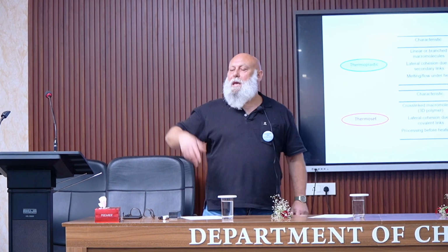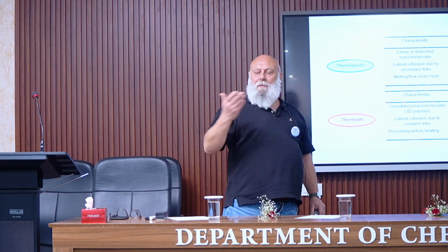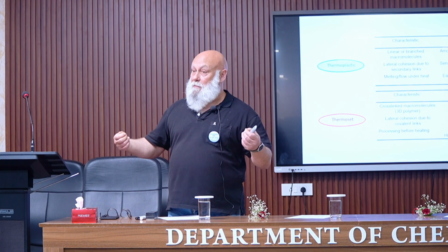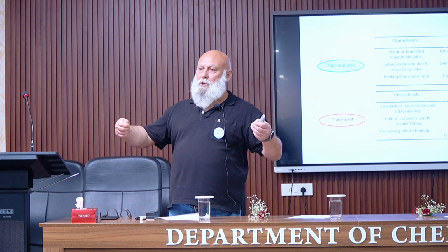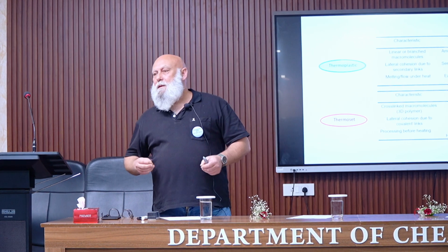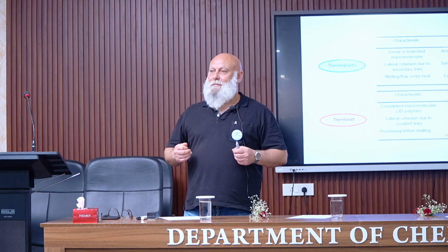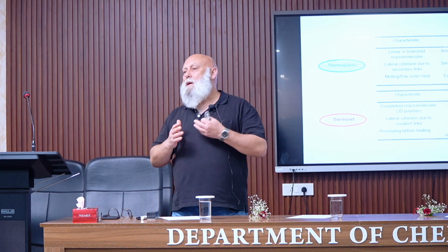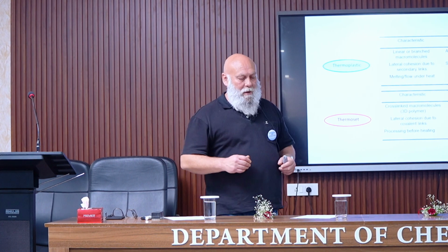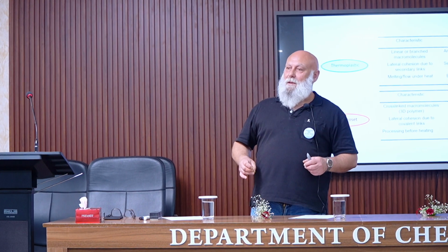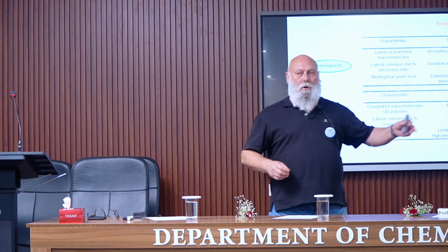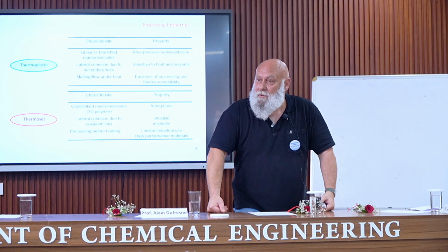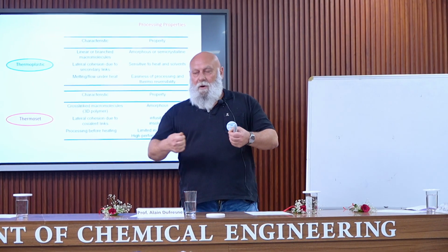The characteristic of an elastomer is that it is easy to deform, okay? And the deformation is reversible. Why is it easy to deform? Because it is easy to break the intermolecular interactions, meaning that this material is in the rubbery state, meaning that the glass transition temperature is below room temperature, which is the case for natural rubber with a Tg around minus 60 degrees Celsius. But also, when you deform this rubbery material, you have an irreversible deformation.